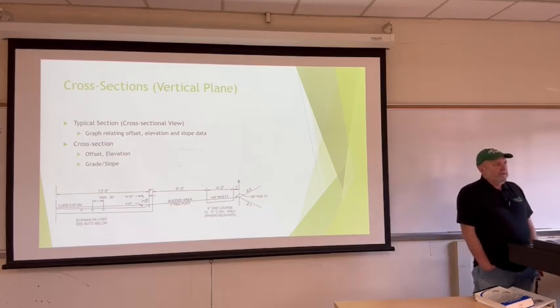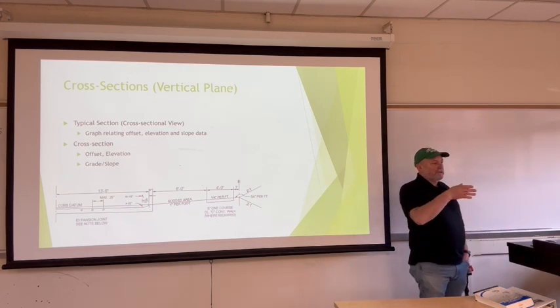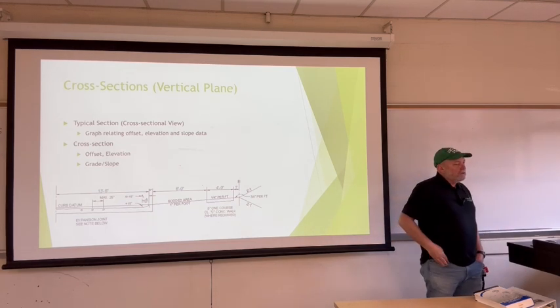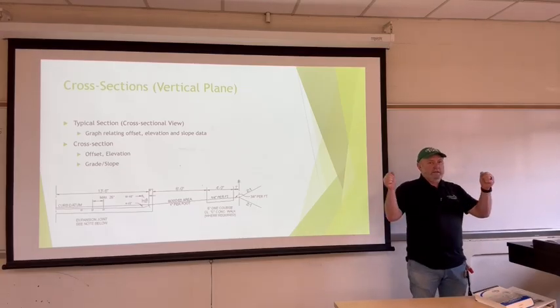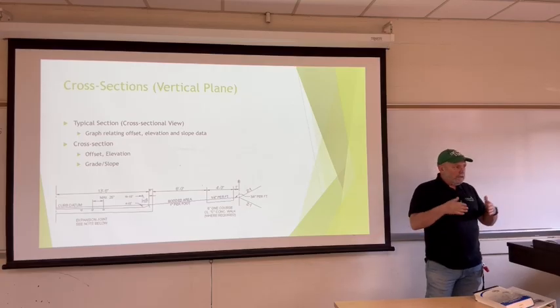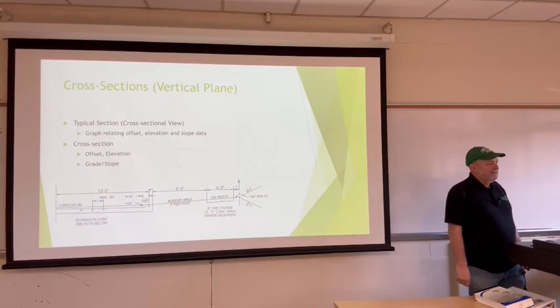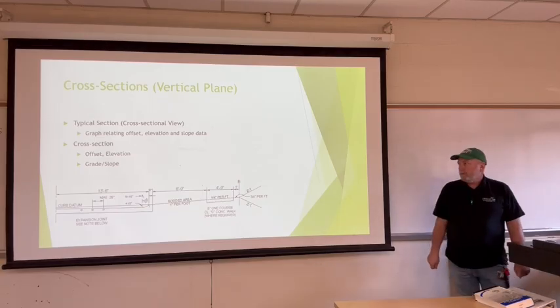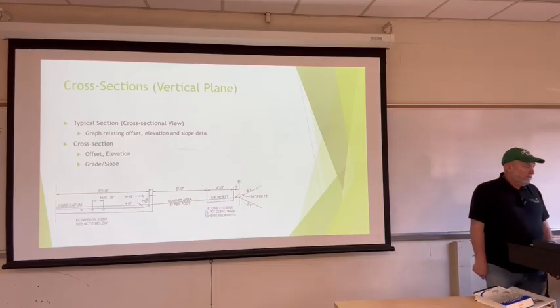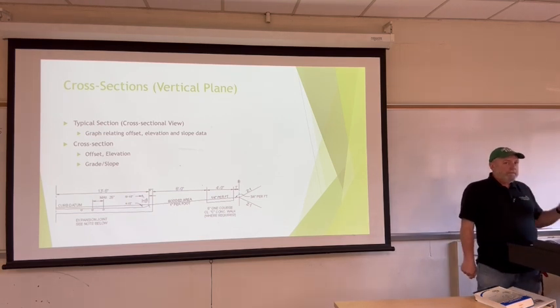Yeah, typically the right of way comes off of the center line of the roadway, or, in the case of power poles cutting across a farm field or something like that, the center of the alignment would be the power poles themselves for an electric line or whatever. And your right of way would typically be labeled off of that. It's like 25 or 30 foot. But yeah, they measured 30 foot on the pavement when it should have been 15. So they were all out in the middle of everybody's yard.